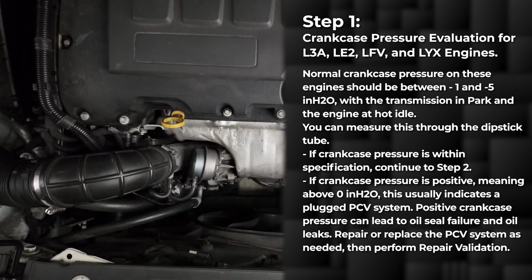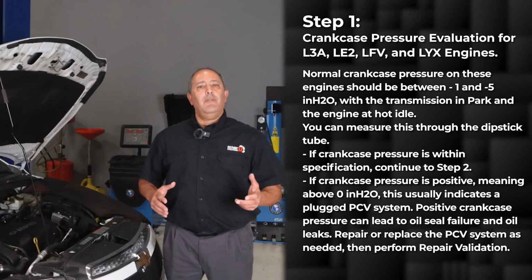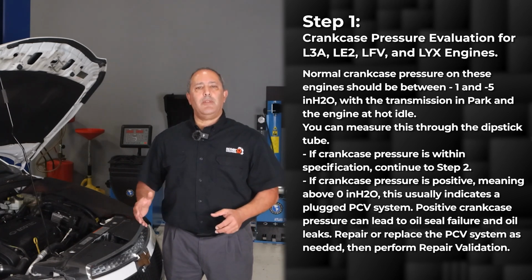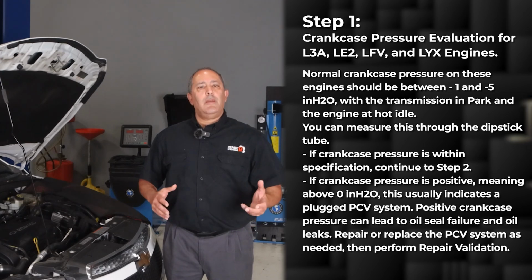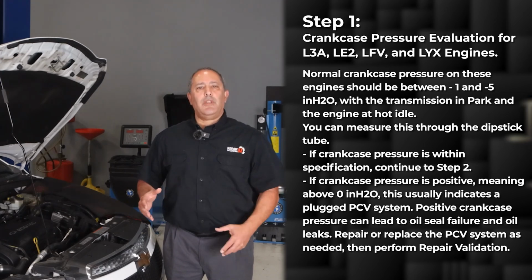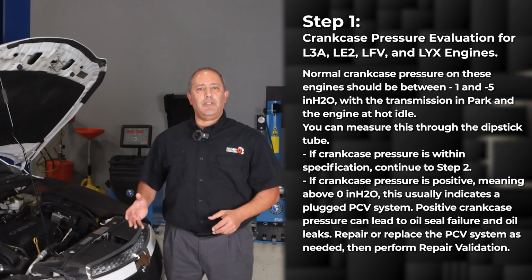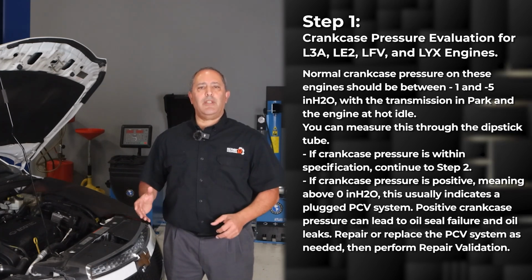However, if your crankcase pressure reading is outside the specified range, especially if it is positive or above 0 inches of water, inspect the PCV system for restrictions or failures. Positive crankcase pressure can lead to oil leaks and seal damage. Repair or replace the PCV system as necessary, then perform repair validation.